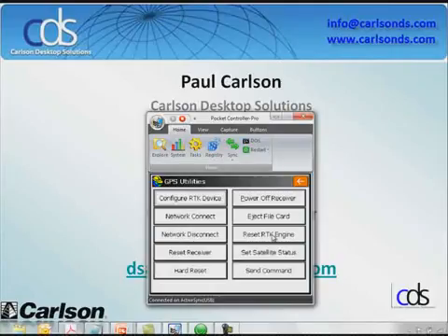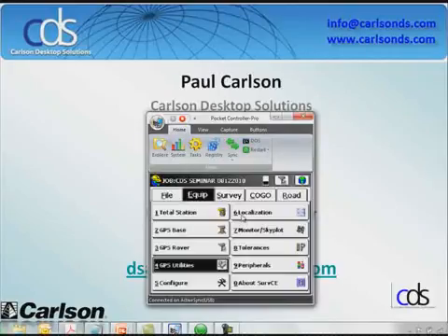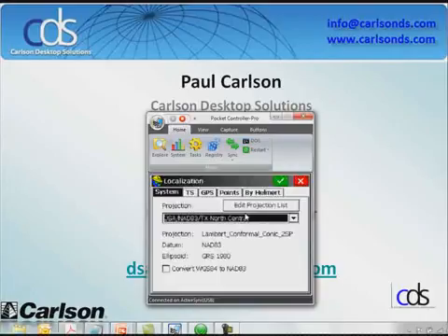The reset RTK, this is the same thing in monitor SkyPlot. It's a little redundancy, but hey, it's there if you need or want it in both places. Okay. The other thing here is the localization. Now this is going to look a little bit different from what you're used to seeing in older versions of SurvCE. For example, I have the ability to go ahead and set my projection. Same thing we see under the file, under the job settings. Same stuff that's there. I have the ability to load a predefined or create a custom projection.